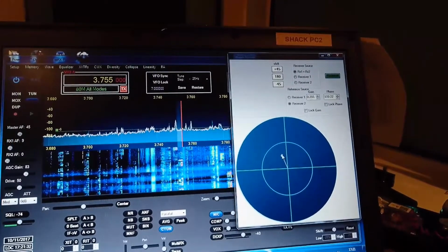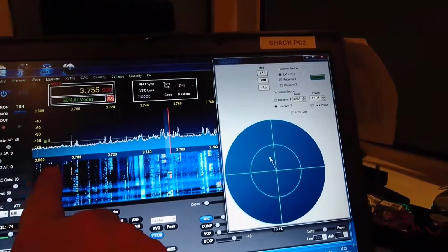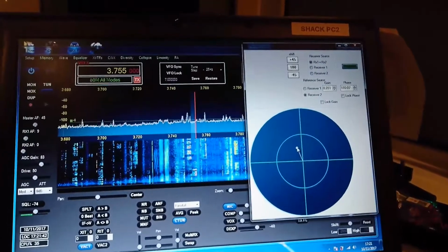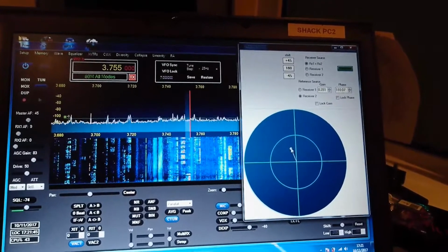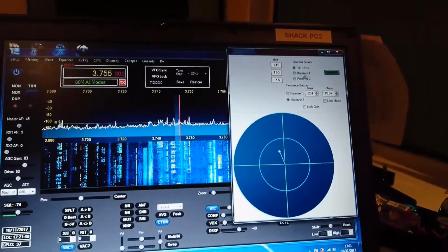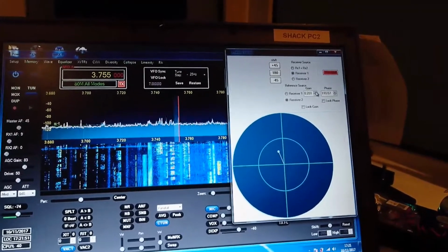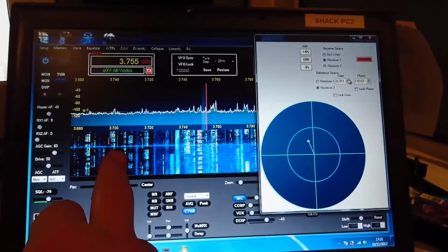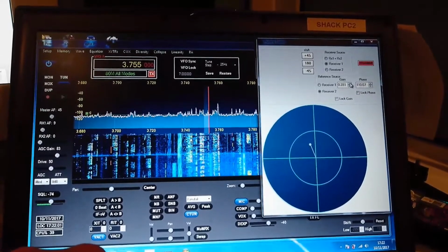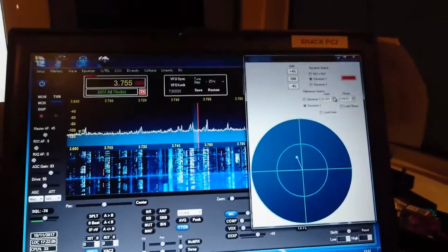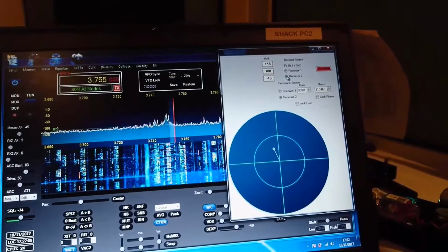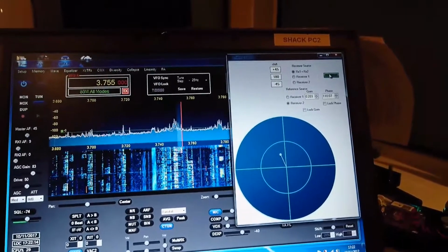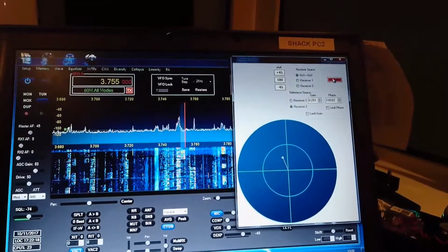And at this point, somewhere around about here, I completely lose the data carriers, the heterodynes that are coming in from the VDSL. Okay, and if I just turn that off and go back to just receiver 1, which is my main receiver, you'll see overall higher noise floor. Okay, that's with it in. You see the lower noise floor, and that's with it out.